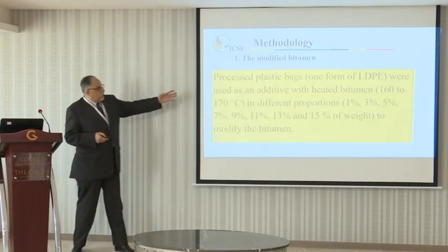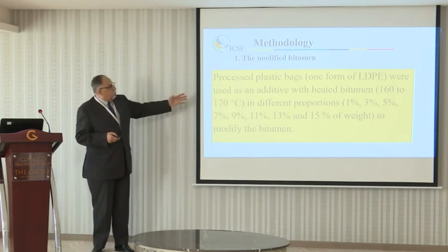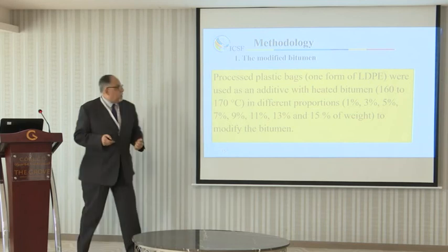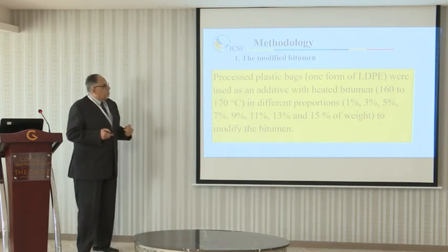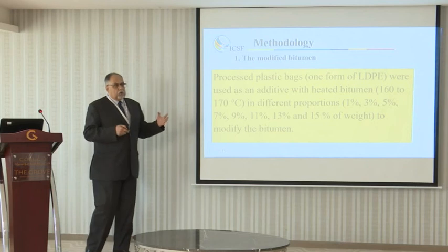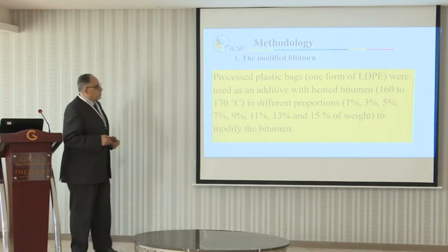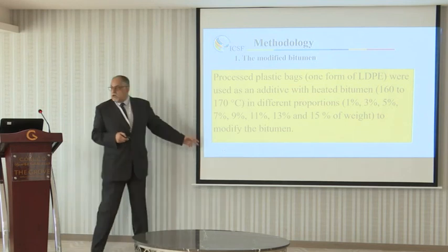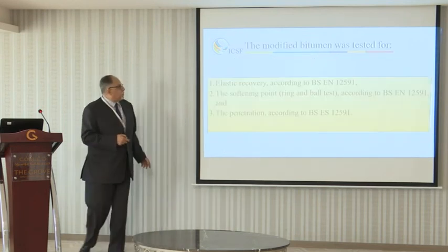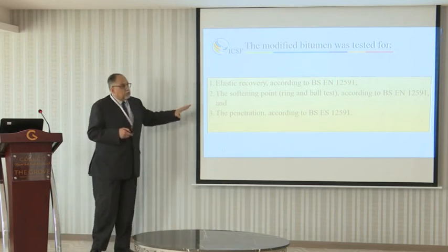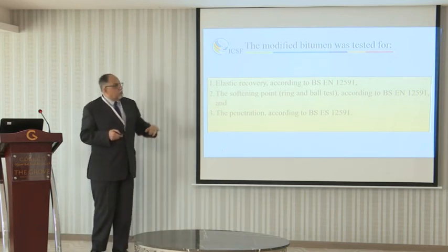The LDPE used was waste plastic bags, or low-density polyethylene bags, and it was mixed with bitumen in certain percentages, and that's what we call modified bitumen. We focused on this binder to test the elastic recovery.